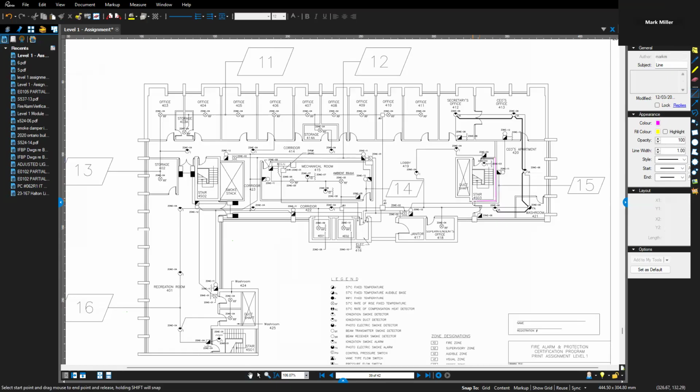A stairwell, let me make that whiter and more opaque. There we go. A stairwell has a fire separation. We know that. And since it has a fire separation, it gets its own zone. Right? So I draw in the fire separations around the stairwells.